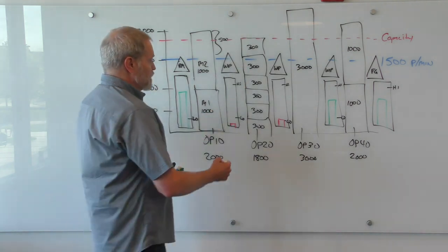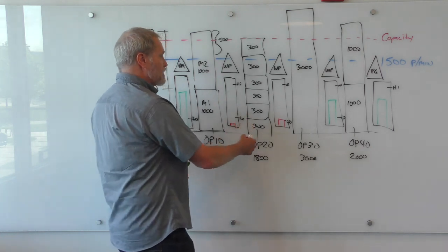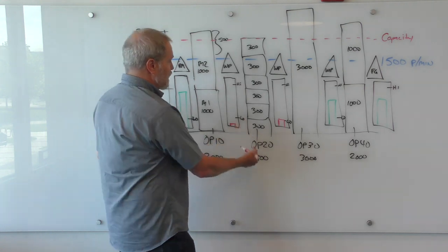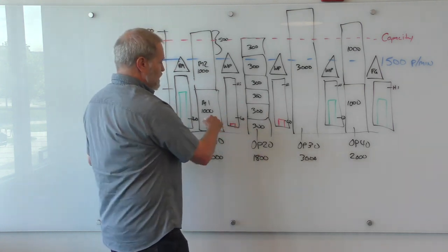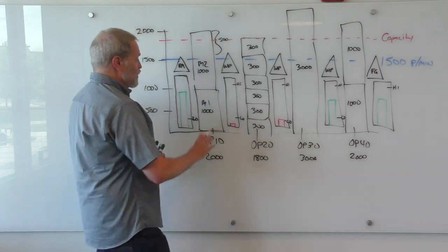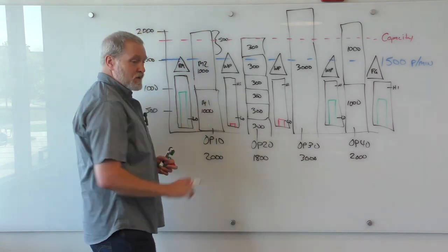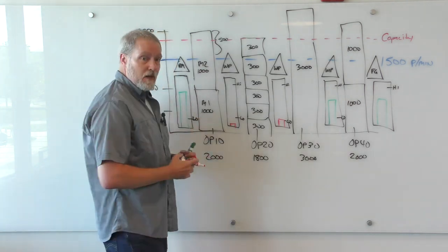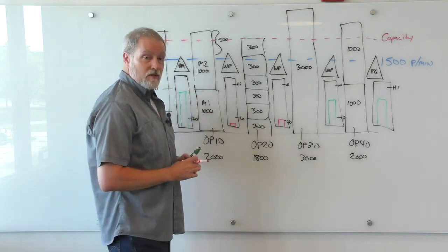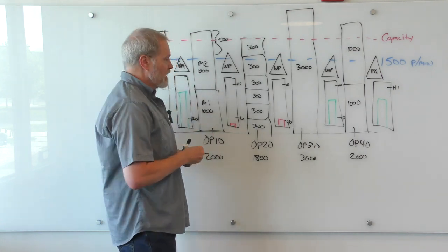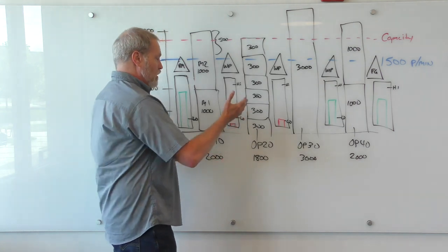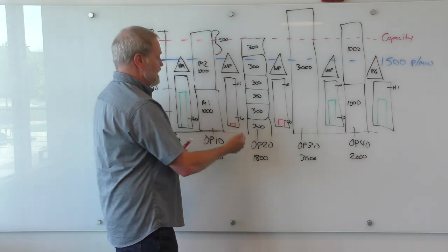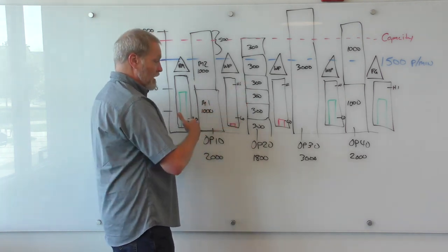So in that case, to understand the root cause of our downtime or our inefficiency, we have to look upstream and say, well, what is causing the problem here? It could be that one of these two machines is in a standby state. It could be starved of raw material, so it could be a raw material problem, or it could be that one of these machines is under a changeover or a downtime event. So the assignable cause for why our process is not performing at capacity is upstream from the process.